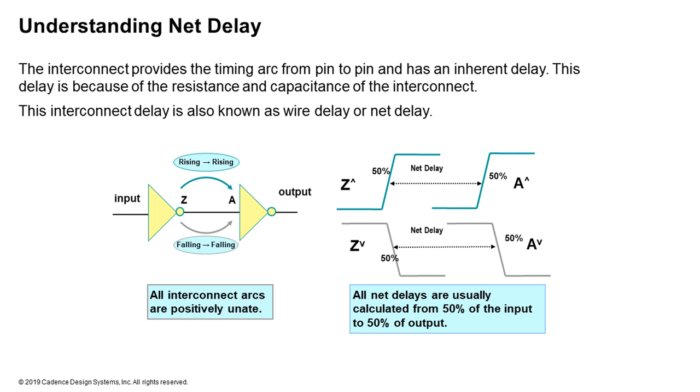And when you want to combine all of these different timing arcs into one single path, you actually traverse through the nets, through the cells, and so on, depending on the transition that is happening, whether it's rising to falling, falling to rising, rising to rising, or falling to falling. And all of these different combinations combine, and most tools use these different rising and falling calculations and look for the worst case delay, and that worst case delay for the entire path is what's used later on for verification against the timing constraints.